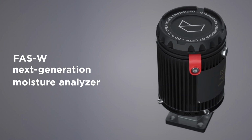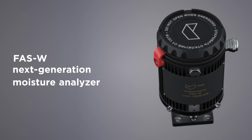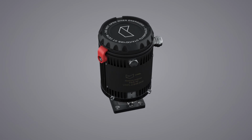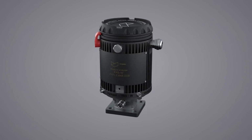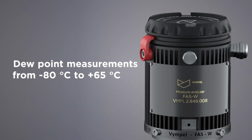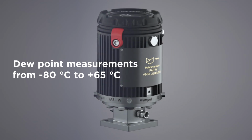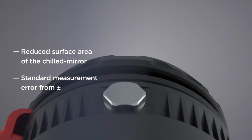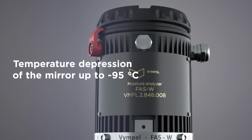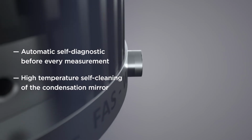The FAS automatic analyzer provides a combination of advantages. This compact and economical chilled mirror solution provides superior measurement results for process applications. The FAS can report gas humidity in terms of dew point and volume fraction of moisture. This analyzer can measure dew point over a wide range with an increased sensitivity to water vapor condensation. This ability is achieved through a reduction in the surface area of the chilled mirror, making it possible to lower the temperature by up to 95 degrees Celsius. This is an unparalleled degree of cooling for an online condensation hygrometer.